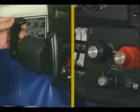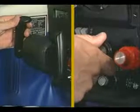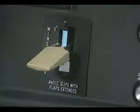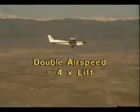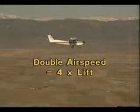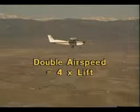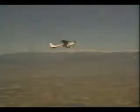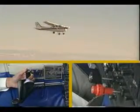You, as a pilot, can control lift by changing individually or in combination the airplane's airspeed, its angle of attack, and the wing configuration, such as lowering the flaps. If all other factors remain constant, doubling an airplane's airspeed develops 4 times more lift. This increase, however, is not without its drawbacks, since any increase in lift also results in an increase in drag. In addition, with all other factors remaining constant, an increase in angle of attack increases lift. For lift to remain constant, airspeed and angle of attack must be used in conjunction with each other.